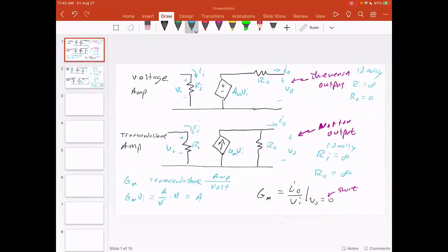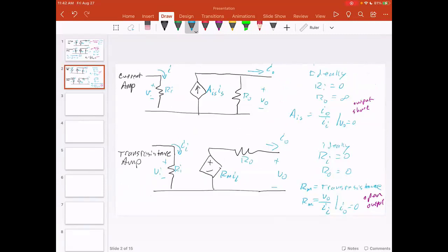So in the case of a transistor, the transconductance amplifier works by far the best to represent a transistor. So we usually use it for a transistor, but we could transform it into one of these others if we wanted. And in fact, a BJT can also be considered as a current amplifier. So a BJT can also look like a current amplifier. And sometimes it makes more sense to use this equivalent circuit for a BJT. It just depends on the situation and what you're doing.